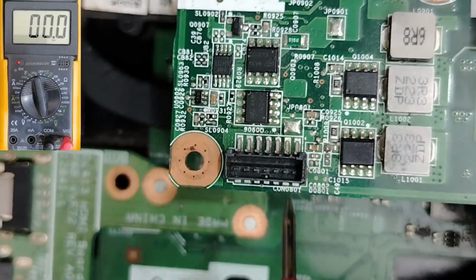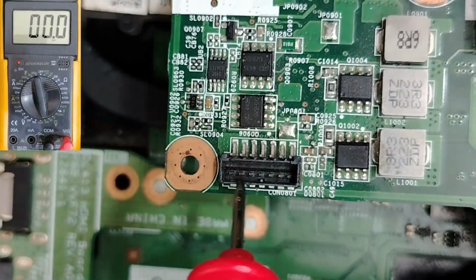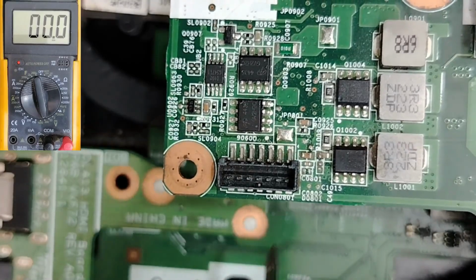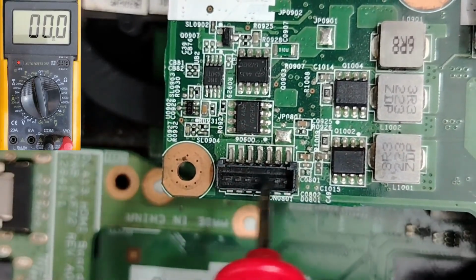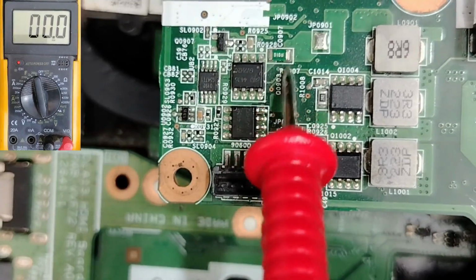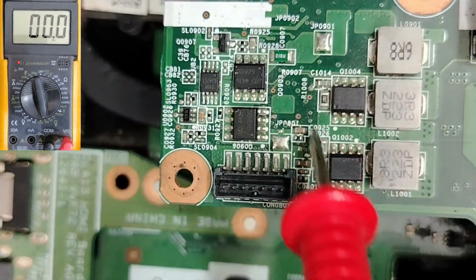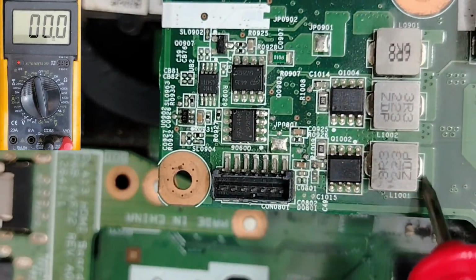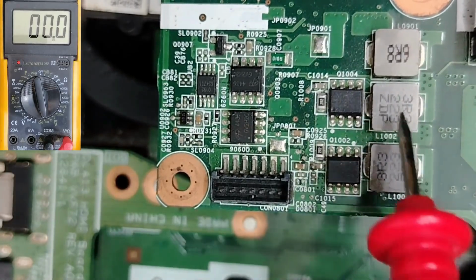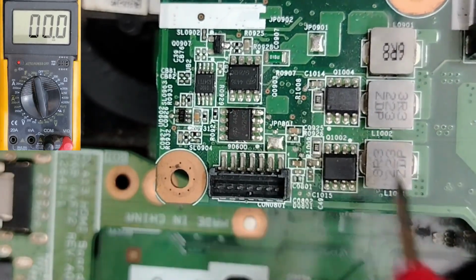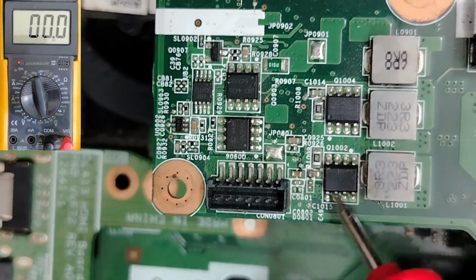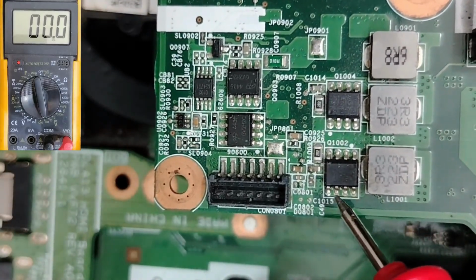So guys, always the same working principle. I show you many motherboards in order to master and understand 100%. So we have the connector, this is the input connector. After that, we have two switches. After that, we have the current sense resistor, guys. And then, as you can see, we have the 3 volt, 5 volt circuit. Why? Because we have here a duplicated channel. This one and this one: inductor, MOSFET, resistor, capacitor; inductor, MOSFET, resistor, capacitor. So for 3.3 volt and 5 volt, you will find always a duplicated channel.